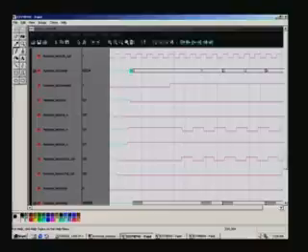So, for example, you need to select the chip, so we make the chip low, as in the test bench we had made here, and RW1 is in write mode, as we have seen it is low, and the chip is enabled all through. The write pulse applied here corresponds to the 0 address, and it is applied after the positive edge of the clock. Address is always applied at the positive edge, you can see here, and always at the positive edge the address is changed, whereas the write pulse is applied only after the address stabilizes.